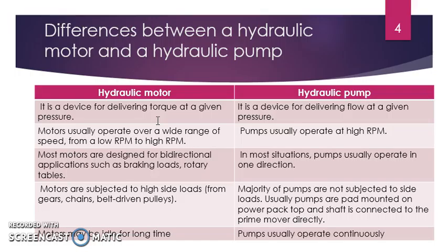Most motors are designed for bidirectional applications, but pumps usually operate in one direction. Motors are subjected to high side loads, but pumps are not subjected to side loads. Motors may be idle for a long time, but pumps usually operate continuously.